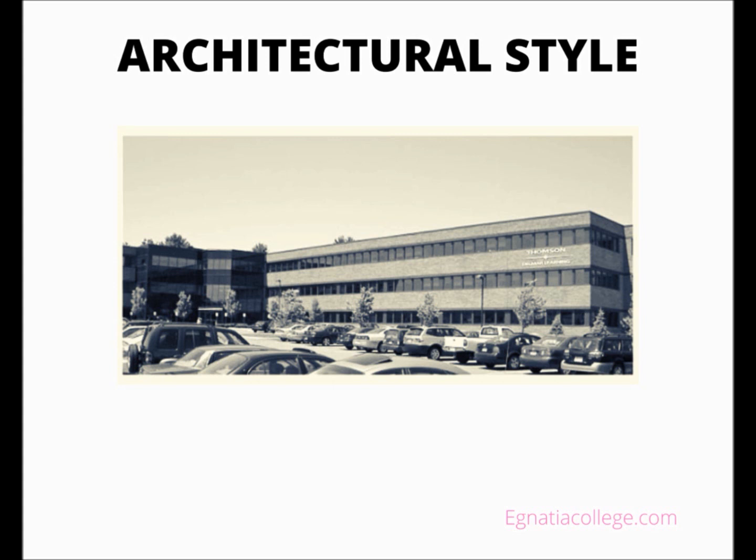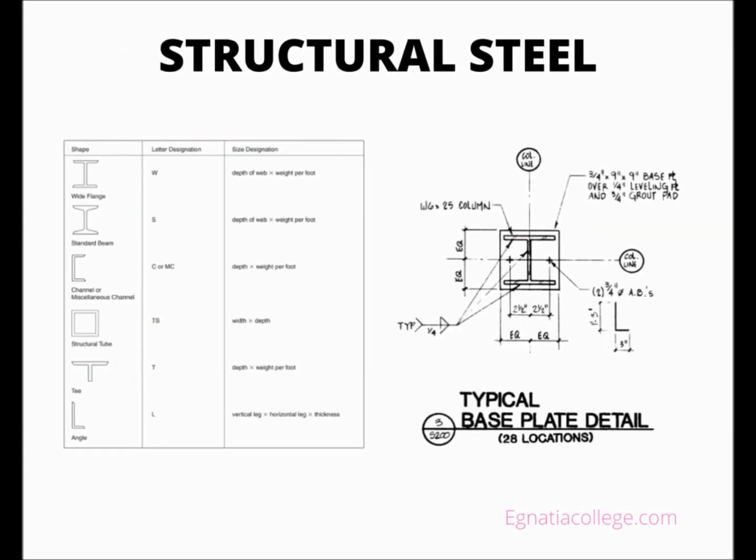Structural steel. Steel is made by alloying small amounts of carbon and other elements with iron. The amount of carbon in the steel determines its toughness. Other elements, such as chromium, copper, nickel, or titanium, are used to produce specific properties. Alloying chromium with the steel, for example, makes stainless steel. Structural steel is mild steel, a small amount of carbon is used, that is rolled into specific shapes used for construction. The most common structural shapes are shown in this figure.